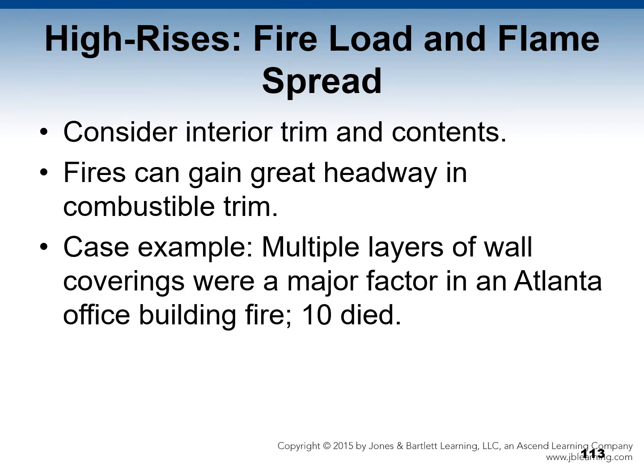Continuing with high rises in terms of fire load and flame spread, consideration should be made of the interior trim and contents. Interior finish is often installed by the occupant without a building permit. Fires can gain great headway in combustible trim. One example is multiple layers of wall coverings that were a major factor in an Atlanta office building fire in which 10 people died. They had wallpaper on top of wallpaper on top of paint on top of wallpaper on top of paneling.